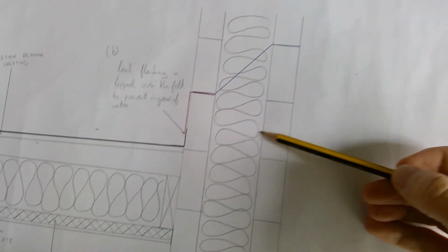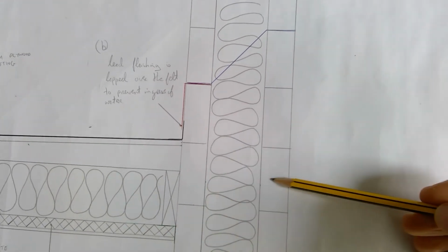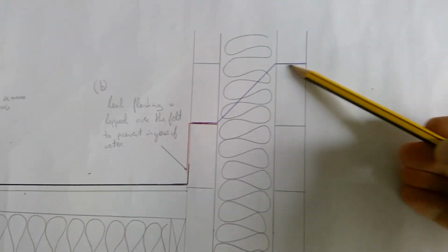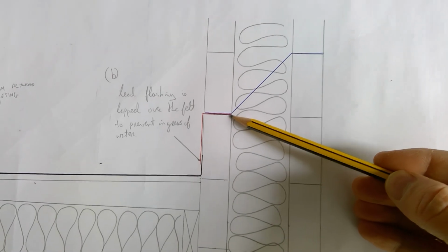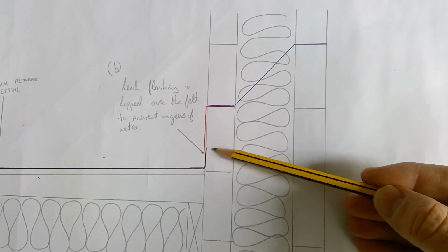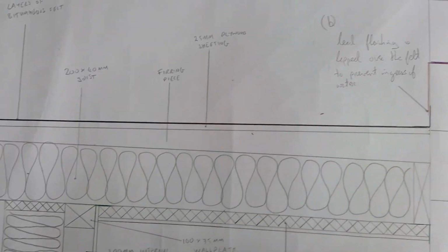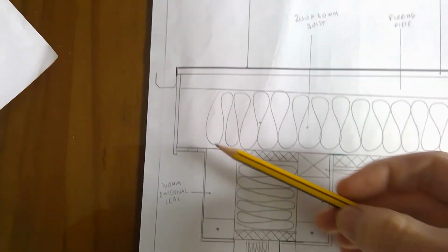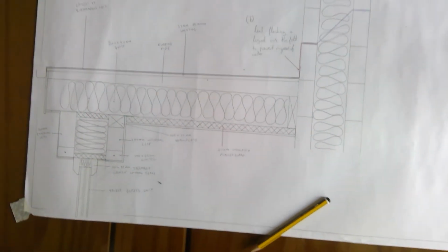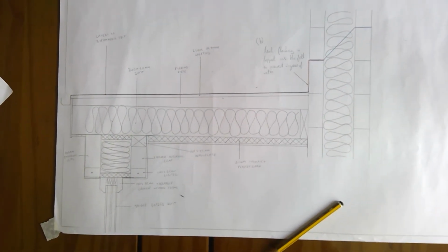I have the full wall here now. Make sure you get that full wall, and I just ran out of space in my sketch. There's the DPC running over there. The red pen is the lead flashing. The black is the bituminous felt. You can see the little angle on my fairing piece, and there's the eaves area here, so the fascia and the soffit. Let's show the full solution there and work your way through that question.